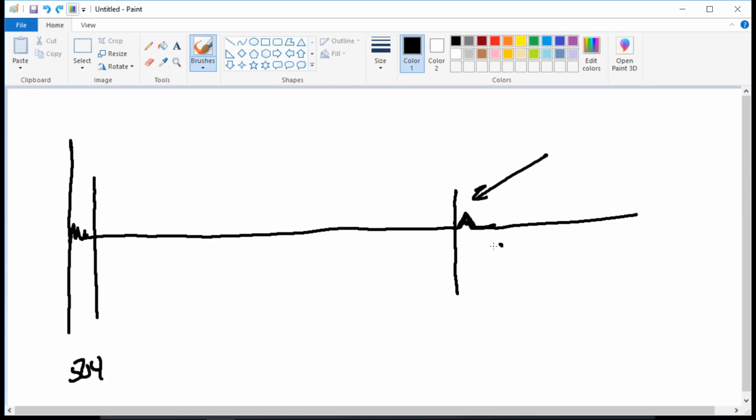Pulse it again, or what's the term you used? Charge it to see where the fault's at. We're in radar mode. We're not charging it. What did I write on the screen? Ground it. There you go. If I have my machine and I tell the guy by radio, hey man, ground the far end, I'm going to draw this end of the line right here.